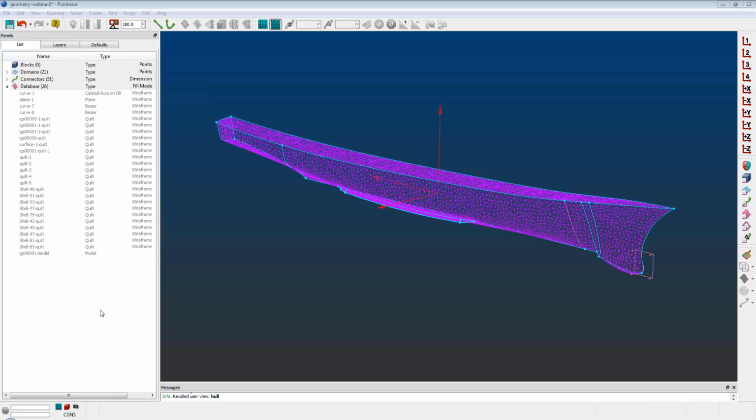Now, the second way to answer that is like I did at the beginning. If the overlaps are so gross, like we had two surfaces that were grossly overlapping, in that case you don't want to use the merging and the model assembly. You're going to want to actually modify the surface and trim it. So the first step, like I did, I split the overlapping surfaces because it was grossly overlapping. In the other cases, yeah, there were gaps, but there also could have been small overlaps. So that would be the approach that I would use for that case. Okay, thank you.